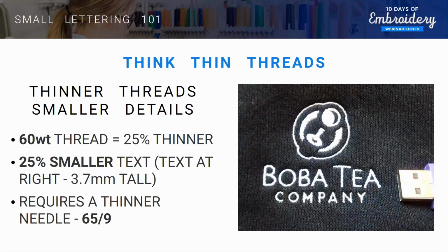So thin threads. Most people have heard, hey, if you've got small lettering, what you really want to do is get some thinner threads, and that's going to help you run. The thing is, you can run thinner threads, but there are some technical things that go on with using thinner threads that you have to be aware of. They aren't just a cure-all, and you can't necessarily just take thin threads and put them in your current design that you already have created and run them. Sometimes that'll help. If your design is already a little too dense, that might work out. But with thinner threads, you really do have to do some adjustments, and you have to be very aware of how they run and how they operate.